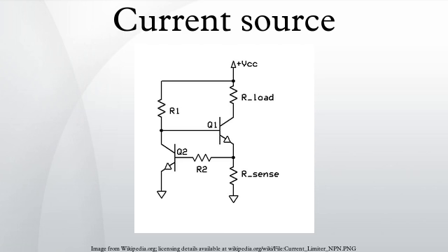This effect is mitigated to a large extent, but not completely, by corresponding voltage drops for the diode D1 in Figure 6, and the LED1 in Figure 5. If the power dissipation in the active device of the CCS is not small and/or insufficient emitter degeneration is used, this can become a non-trivial issue.